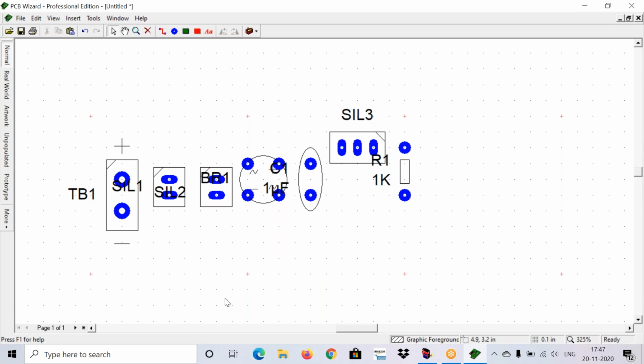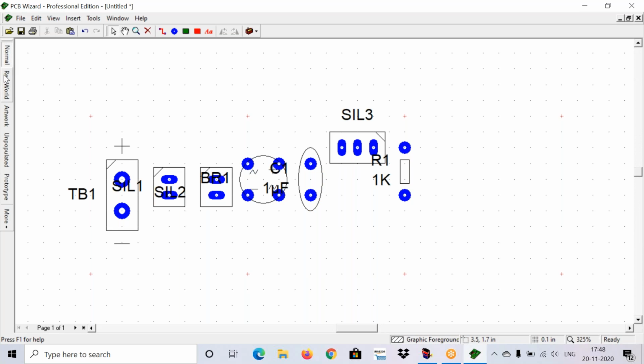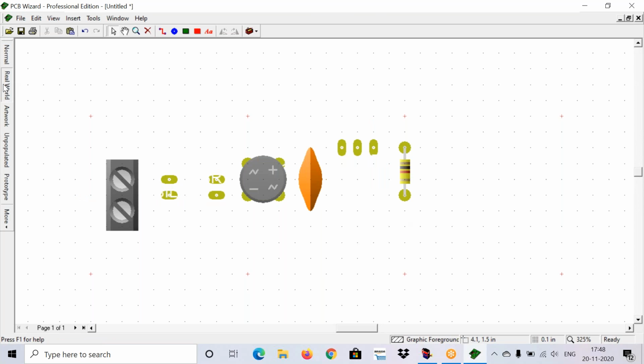Change the places of footprints and design the layout PCB. After that you can give labels. You need to add the copper area and the board area. At last give a label to your circuit as 5V charger. Keep it in normal view, and you need to place 2 pictures when it is completed. Take a picture of the normal design and then place a picture of your real world design also. Is it clear for everyone?